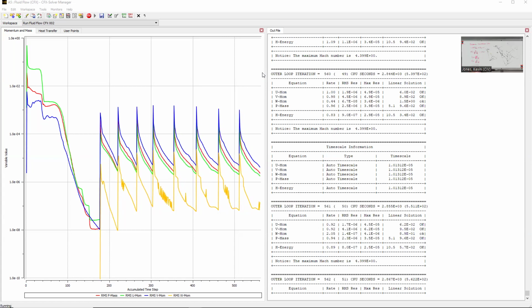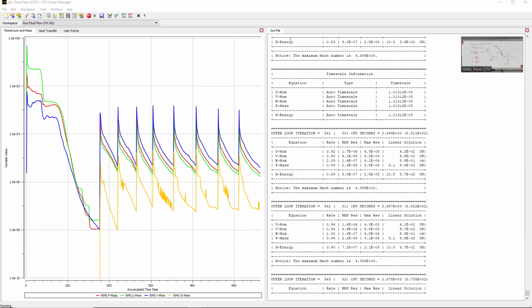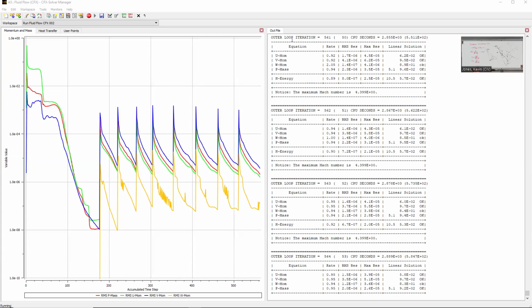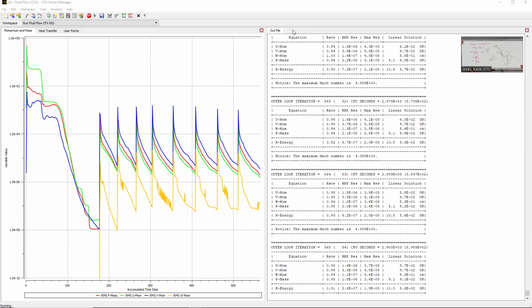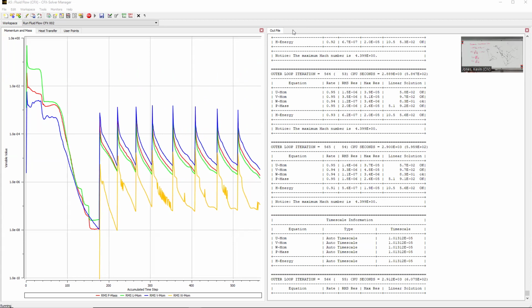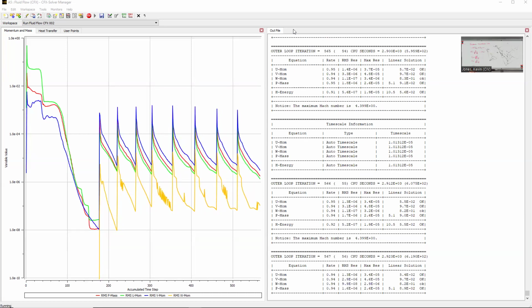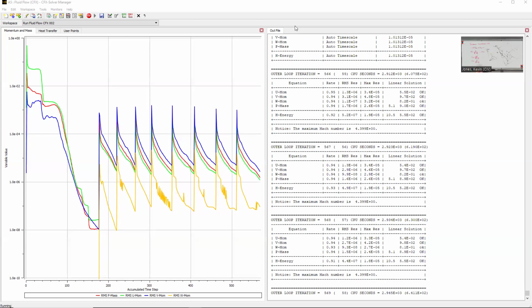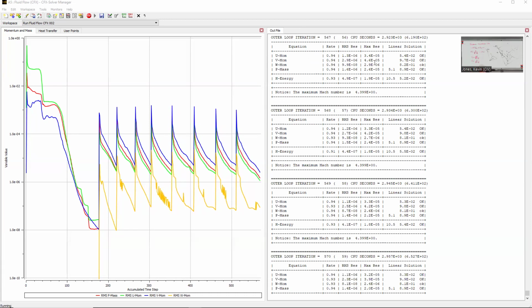In real life, actually, it's not infinitely thin either, but at sea level it's like 15 mean free paths or something like that. So it's microns down here. But by the time you get up to the top of the atmosphere, in low Earth orbit, it's like a couple of kilometers. So there's no air, but the shock is very thick. For reentry vehicles, it can be quite thick.